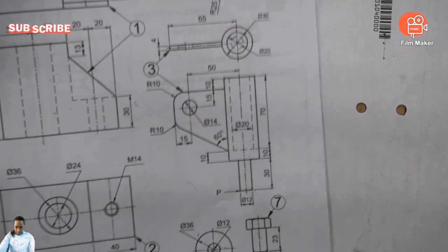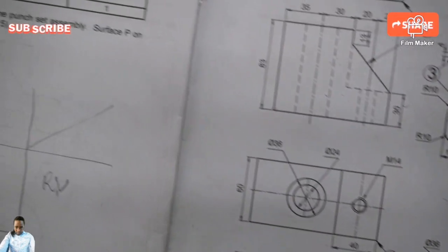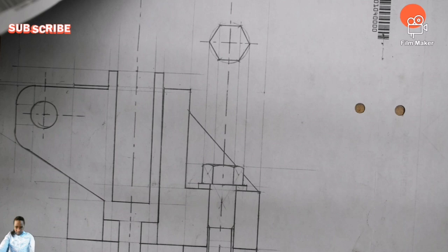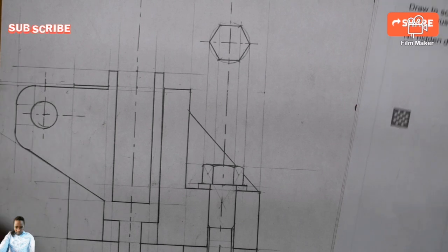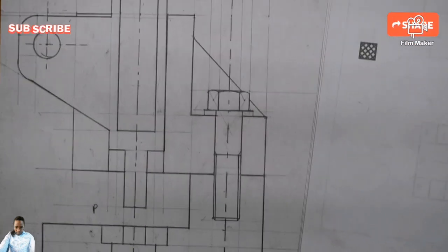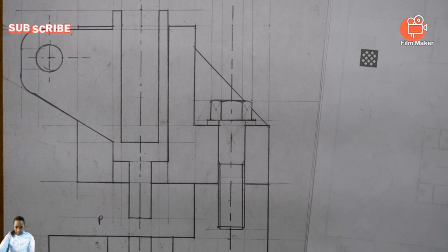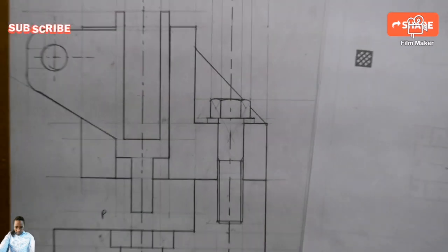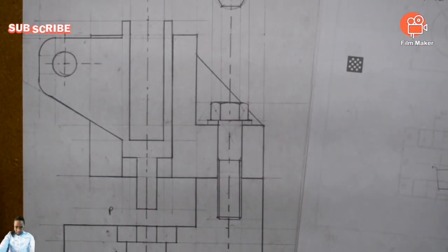So now let's put in item 4. Not 5, sorry, but 4. Item 5 is the cutter die. It's the one that is going to be cutting. Remember, this is the puncher, so this thing is going to have an up, down, up, down type of movement. You understand? The reciprocating. Remember, it's a puncher set. If you know a stationary puncher, how does it work? That is why they said to leave the allowance of 10 millimeter. So item 5 is the cutter die.